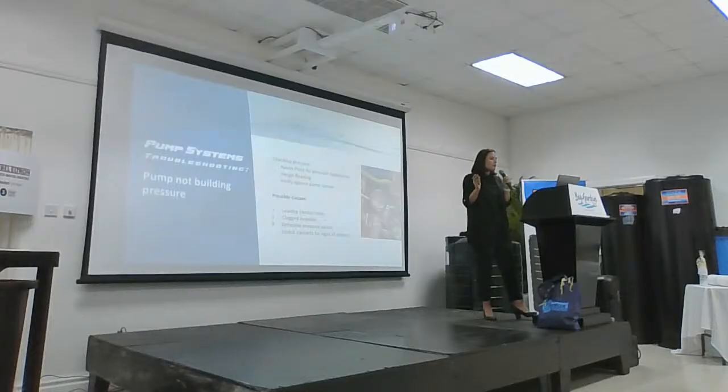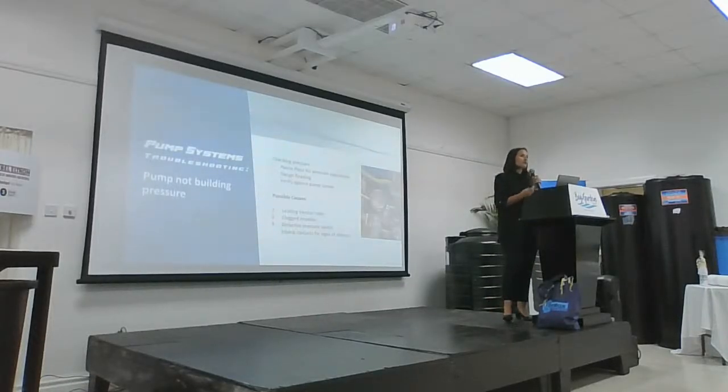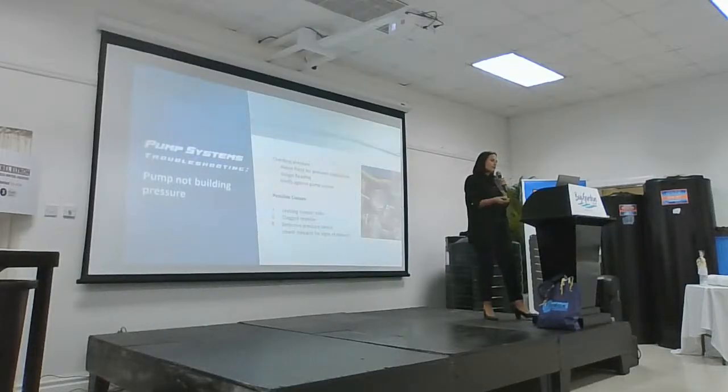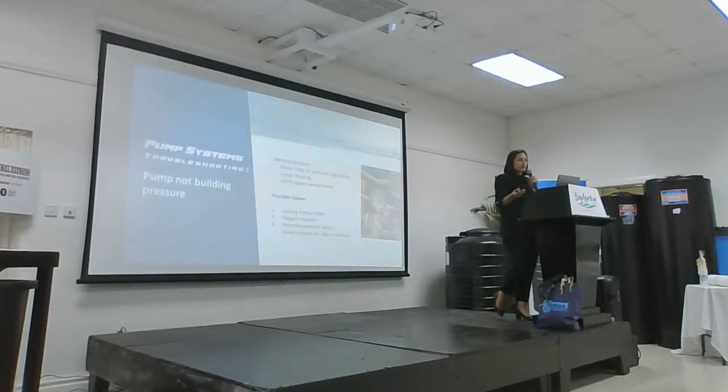There are a couple of possible causes. One, it could be a leak in the venturi tube. It could be a clogged impeller or a defective pressure switch. So you want to check the switch contacts to ensure that it is functioning properly.